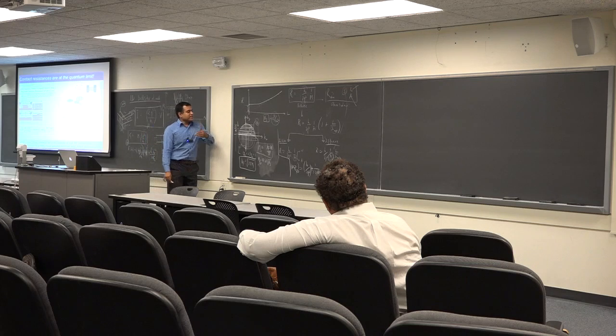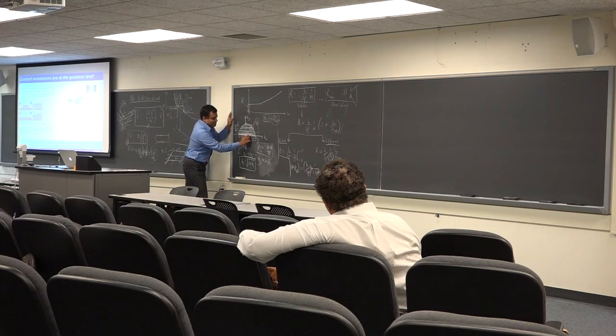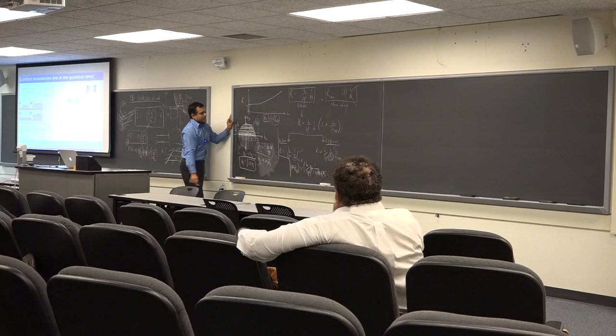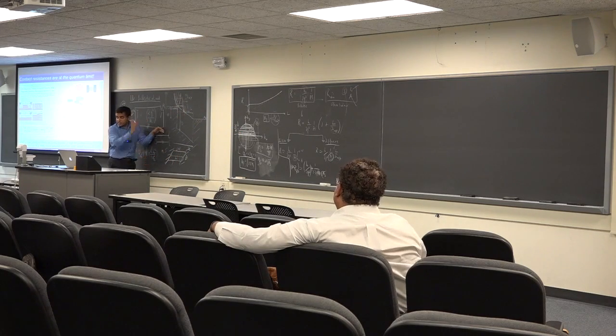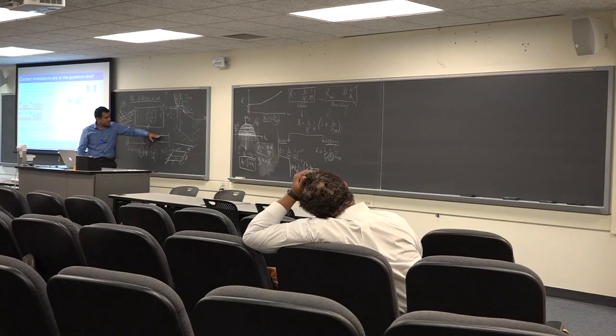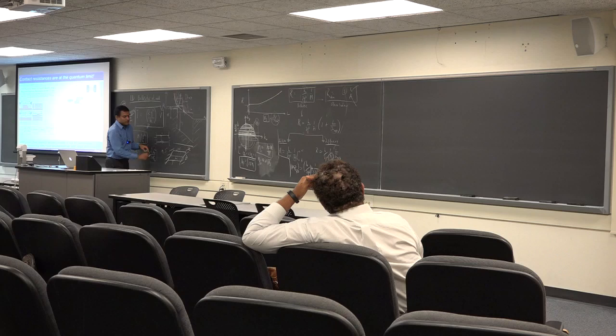Now we've started talking about the ballistic FET, and I kind of cheated a little bit by saying that the number of modes is just exactly that. But this situation, where I have a number of modes, is really not the same as if I had m 1D conductors. Physically, what's different? If I have m 1D conductors separated from each other, none of them are going laterally. They have no chance of an electron going from here to there.